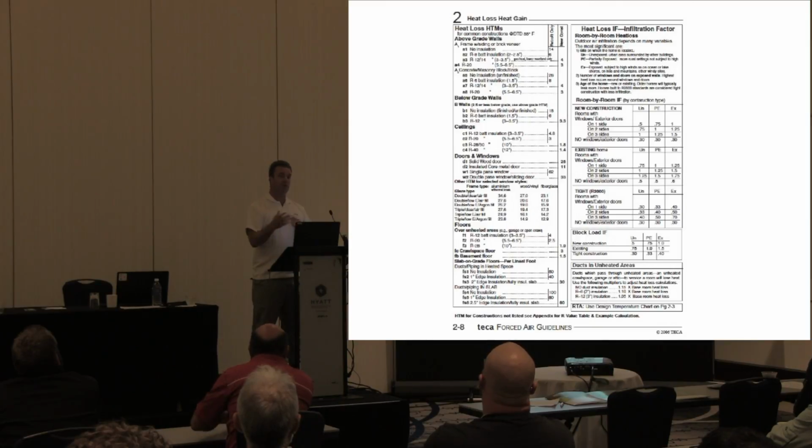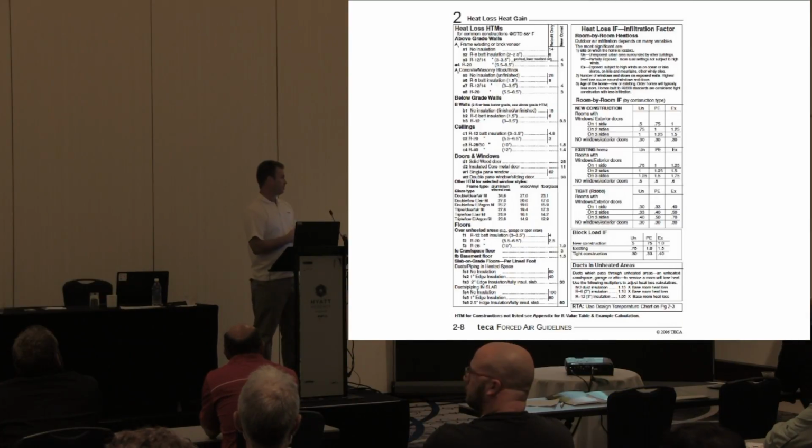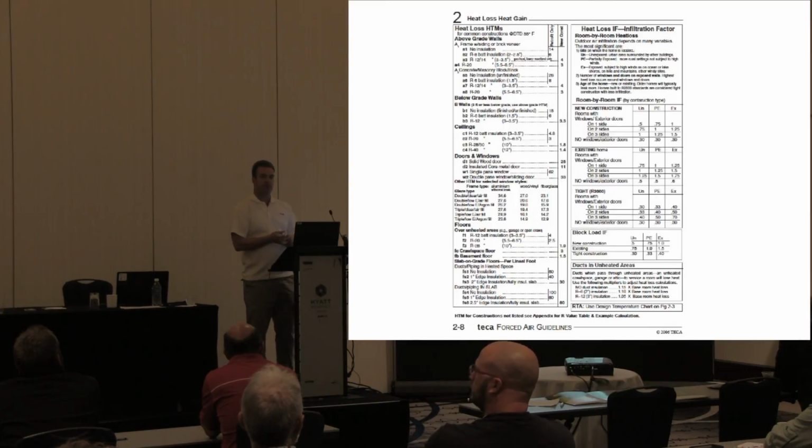And sometimes they're able to cover some of the costs because there still are a few grants floating around for old houses. But you guys, if you're doing new houses or renos, the reno will be adding new code rated windows. So you shouldn't have too many changes from what the thing is. But basically, a low E argon window in a wood or vinyl frame, which is probably the most popular, in double pane is 19 BTUs per square foot per degree Fahrenheit. Whereas if we go to a single pane window, it's 62.